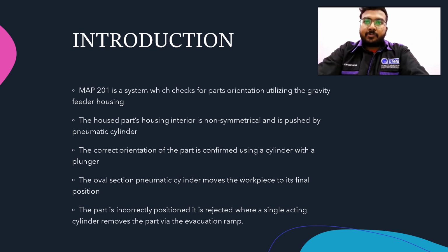Appropriate mapping of inputs and outputs is a critical initial step in PLC programming. It is a very simple process, yet some programmers skip it or fail to perform it correctly. It requires the inclusion of all primary input and output tags in a single program and the ability to manipulate them easily. The requirement for manipulation may arise as a result of hardware failure or as a result of a device needing to be updated or extended.